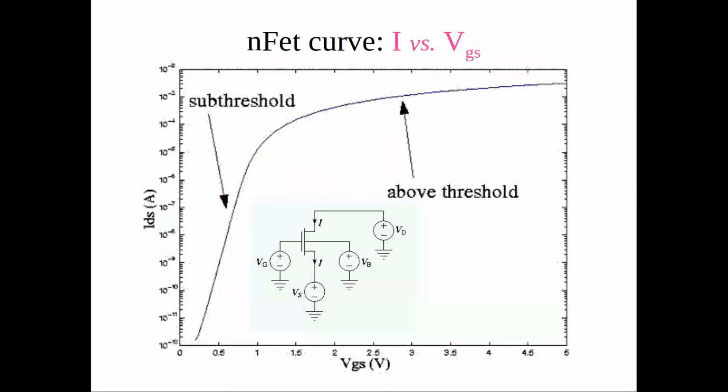Now, what is the catch? What is the price to pay? The catch is, as I told you, it's quite uncommon. It's unusual. If you go to standard electronic courses at ETH or around the world, most courses are teaching how to design circuits in above threshold, in strong inversion, which is this region here, where you have this quadratic term. So it's a quadratic relationship between the gate to source voltage and the current, but on a semi-log plot, you get this sort of saturating effect here. But in a linear plot, you would see a parabola.